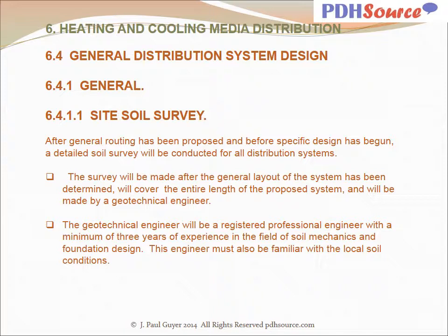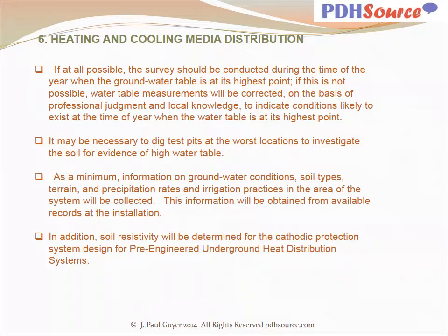The geotechnical engineer will be a registered professional engineer, typically with a minimum of 3 years of experience in the field of soil mechanics and foundation design. This engineer also must be familiar with local soil conditions. If at all possible, the survey should be conducted during the time of year when the groundwater table is at its highest point. If this is not possible, water table measurements will be corrected on the basis of professional judgment and local knowledge to indicate conditions likely to exist at the time of year when the water table is at its highest point.